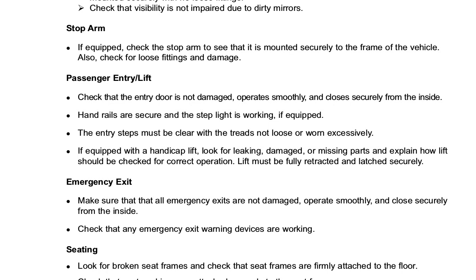Passenger entry lift. Check that the entry door is not damaged, operates smoothly, and closes securely from the inside. Handrails are secure and the step light is working if equipped. The entry steps must be clear with the treads not loose or worn excessively.